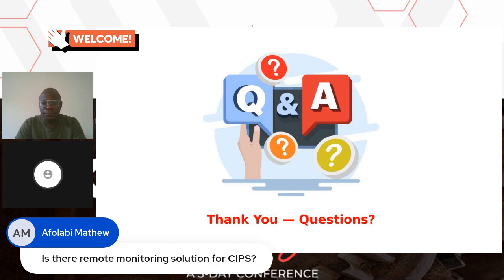Alternatively, you don't need to put a test post. You could just put multiple reference electrodes, because in any case, what CIPS measures is your trailing cable on your test post, and then it measures potentials along every 1 meter or 2 meters, depending on how you are doing your measurements. So the remote monitoring system completely replaces your CIPS, and you don't need to do CIPS surveys anymore. Manual CIPS, that is. It's not manual, it's now remote. Yes, so just to mention.